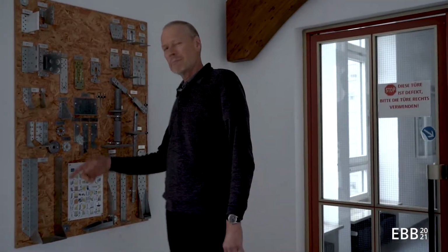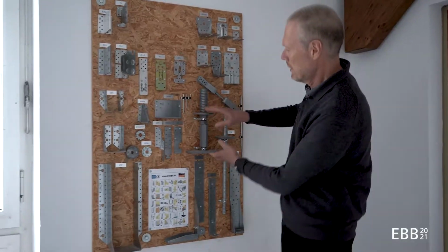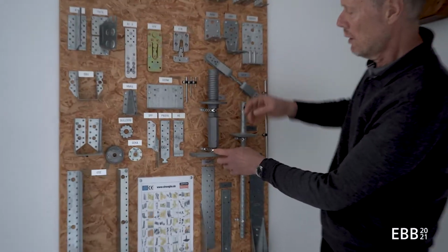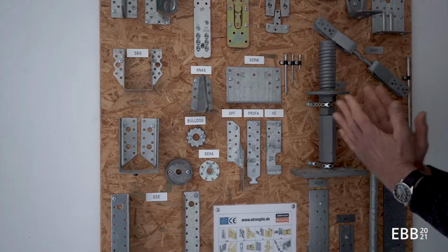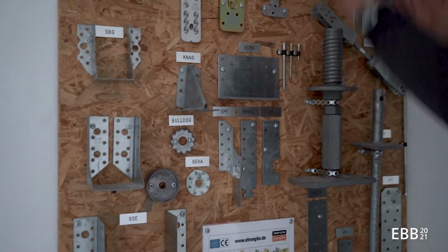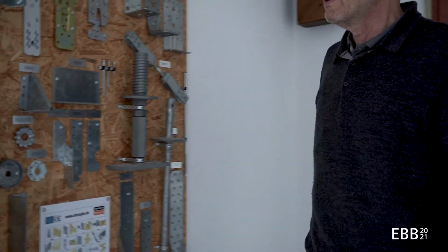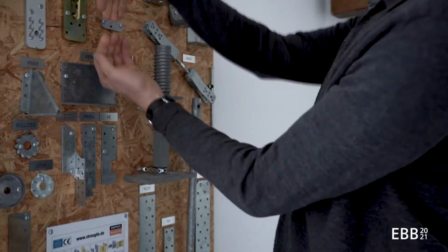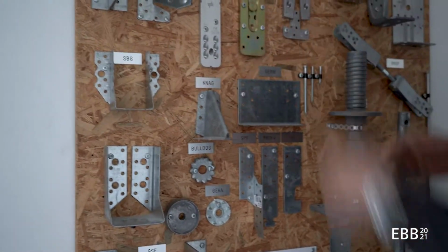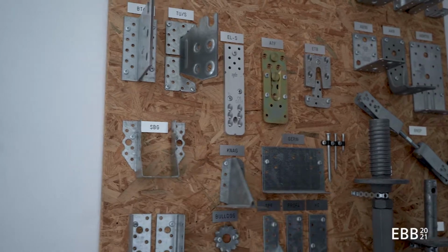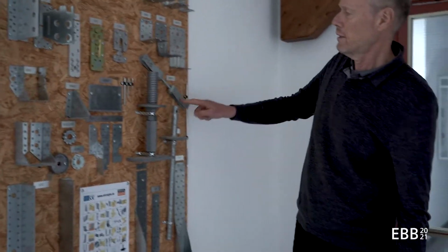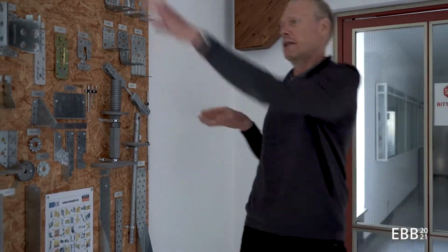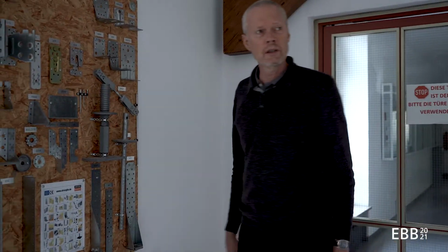So here you can see some articulated joints. For example, this is the foot of a wood column, and you can see that this counts as being articulated because it's so slim in comparison to the wood column that would come above. Here you have a swallowtail link between a horizontal element and a vertical. Same here. You can nail these on the different elements. And here you have a diagonal. And this diagonal will be linked at the angles to the wooden skeleton.